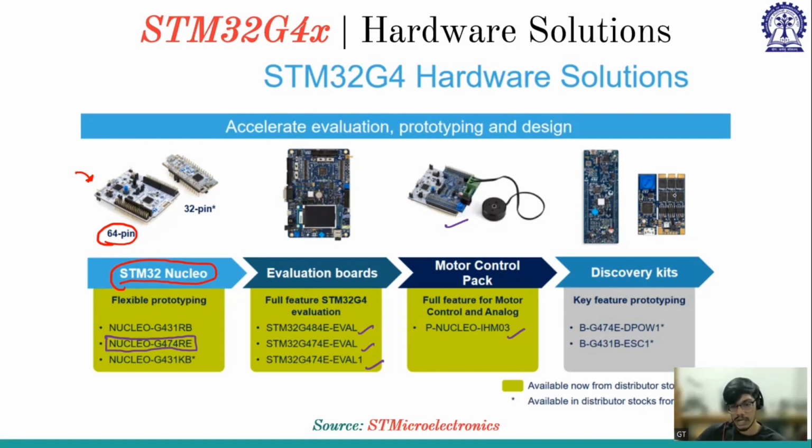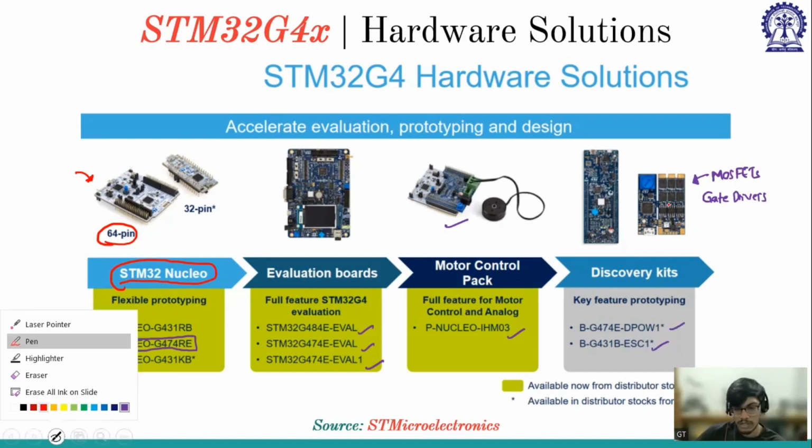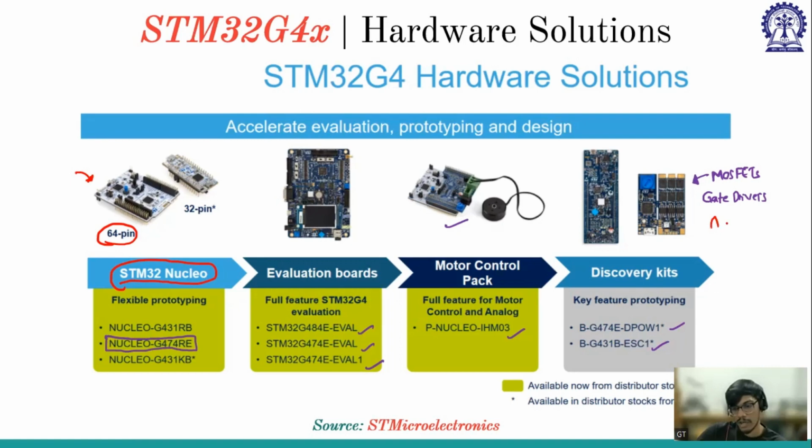If you see here, this is made for some application, and they have mounted the necessary number of MOSFETs and gate drivers on the controller board itself. So you can use these MOSFETs and you can use the controller as well. These are the discovery kits. They are again application specific, so they might have been made for a specific application where you might need these MOSFETs.